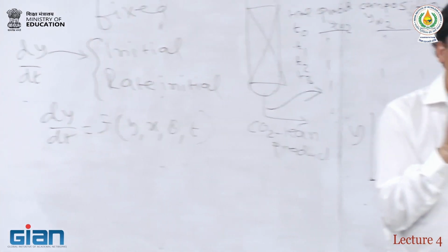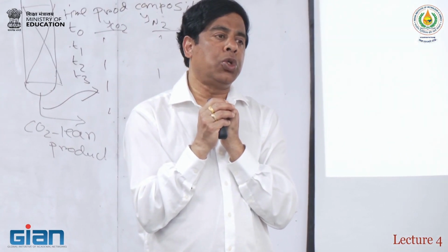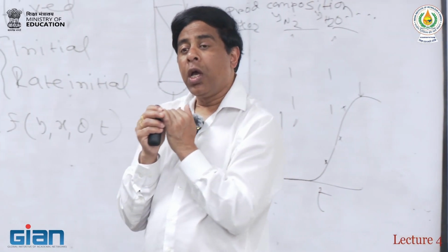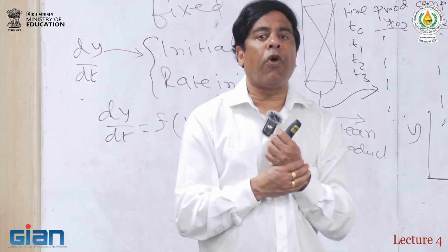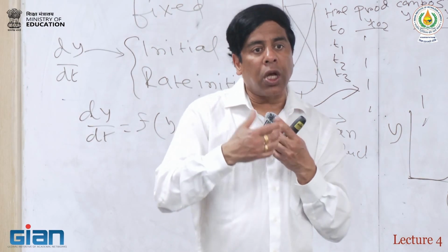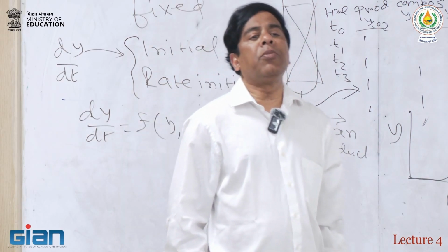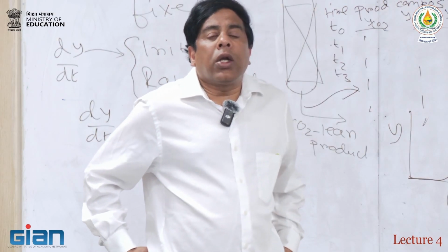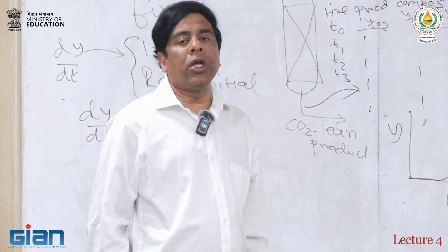It really depends on what that molecule does with respect to the solid and how it interacts with respect to the solid. If you think that the transport essentially takes place only in the form of molecule, then diffusion and the diffusion induced convection, local convection, is the real mechanism by which it will flow. But depending on what other species get formed, the mechanism can actually greatly vary.